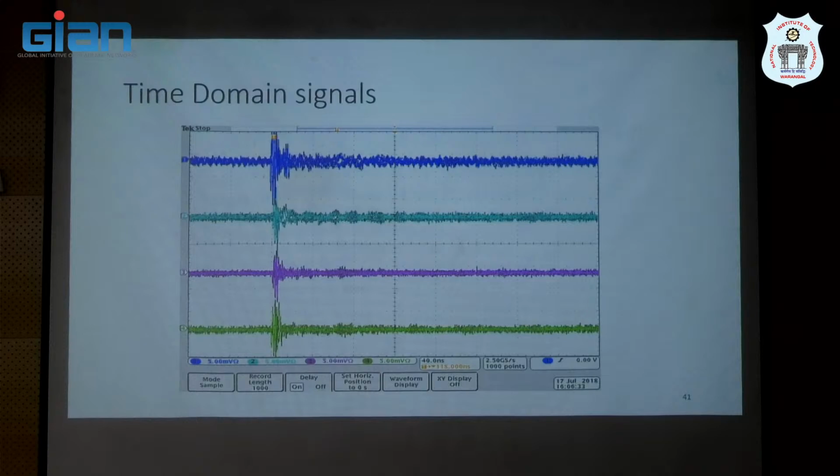Also we can do it by using different sensors. Even nowadays some other types of sensors, fiber Bragg grating sensors, are also being used. The particular wavelength shows, for example, the temperature of the coils, which we want to know. If it crosses a particular temperature, it will show a higher wavelength. In that way you can detect. But the thing is, we have to insert it in between the coil.